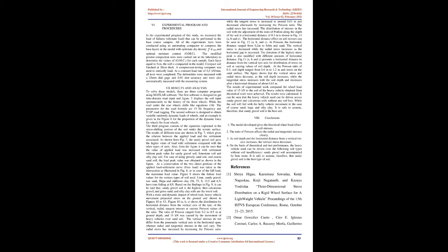The soil deformation sinkage produced under wheels is calculated here by equation 10. The generation of the artificial road input time history x0 of the road profile could be used directly as input to the front wheels. The rear wheels run behind the front by a lag time LT. Subtracting the total soil deformation sinkage from the road profile will modify the rear wheels input as in the following equation.